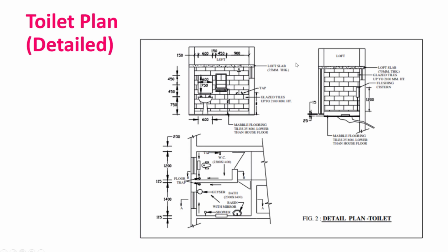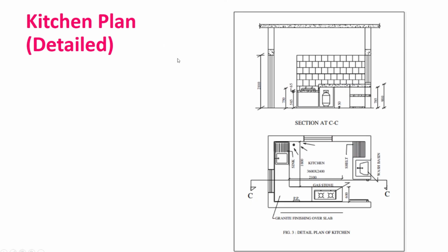Now they have given a certain clarification where the finished ceiling is not provided. Now it can be a normal beam. The underside of the joist or the beam or the tie beam shall determine the upper point of the measurement for determining the headroom. So suppose my room height is 3 meters, then from the floor level to the bottom of the beam has to be 3 meters. Okay, because these are some basic definitions which are given in NBC.